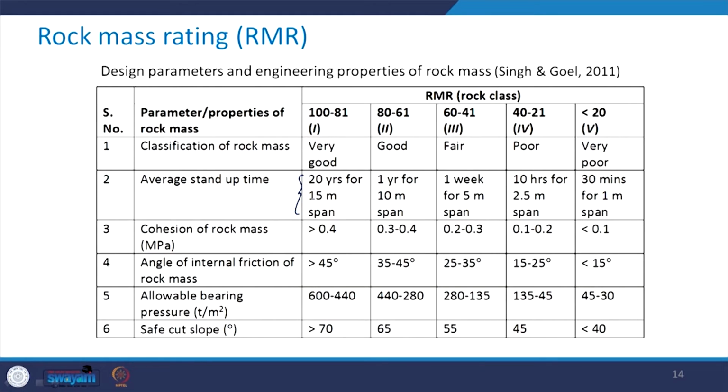Obviously, in case you have very good rock mass, you may have very nominal requirement for the support system. This installation becomes quite crucial in case you have fair, poor or very poor quality of rock mass, because you can see that here it is 1 week for 5 meter span, 10 hours for 2.5 meter span, and here it is only 30 minutes for 1 meter span.